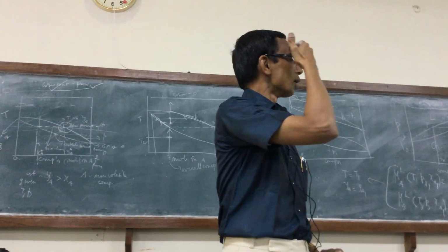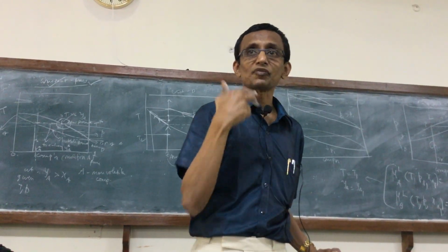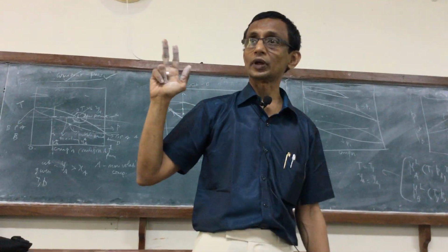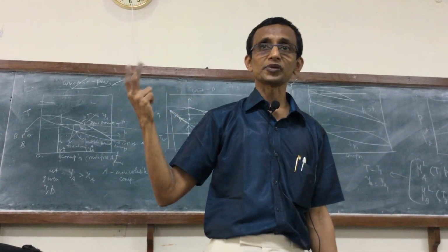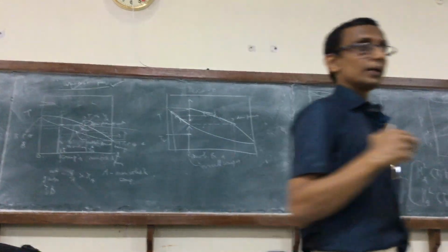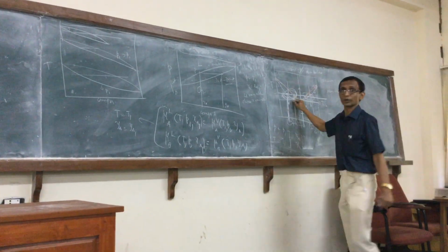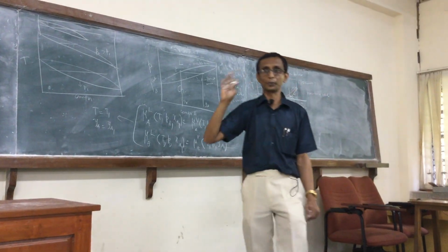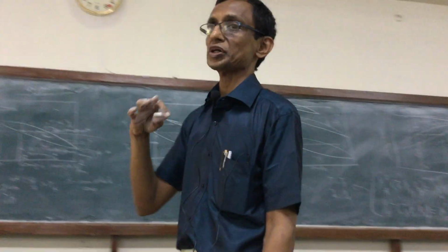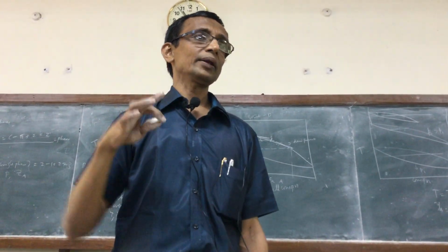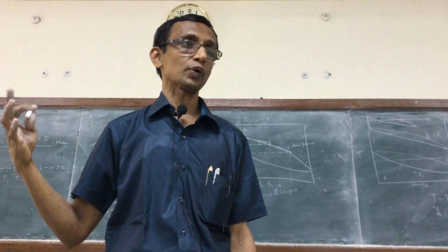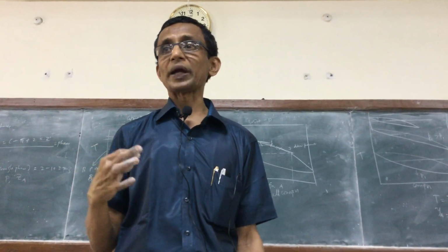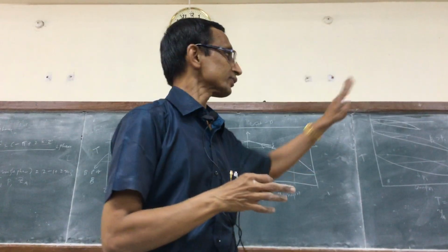What Raoult says is that sufficiently pronounced positive deviations from ideality, which can be related to the activity coefficient being greater than or less than 1, right? The activity coefficients being greater than 1 is called positive deviation from ideality. Positive deviation, he says, invariably leads to a minimum boiling azeotrope, and a negative deviation leads to a maximum boiling azeotrope. But it doesn't mean that just because there is deviation from ideality, it will show an azeotrope. But certainly accounting for a deviation from ideality becomes essential when you have a system exhibiting an azeotrope.